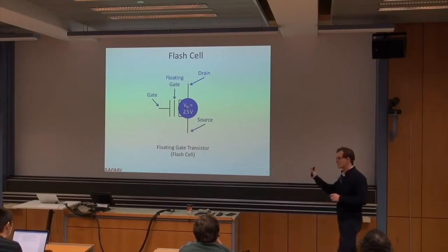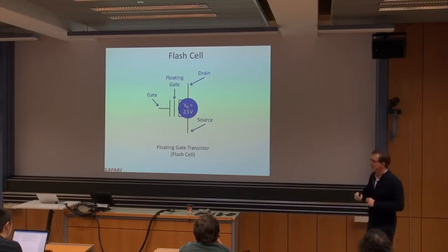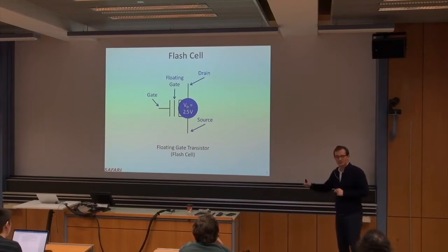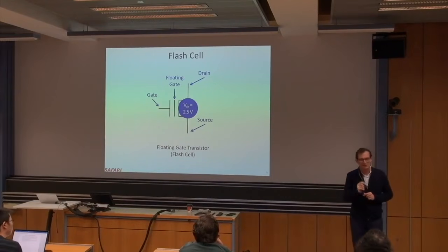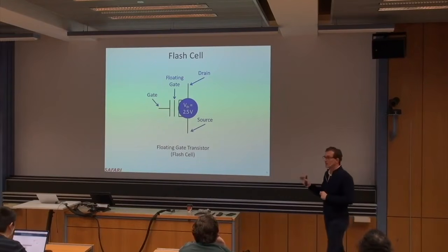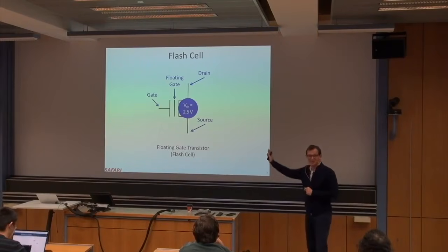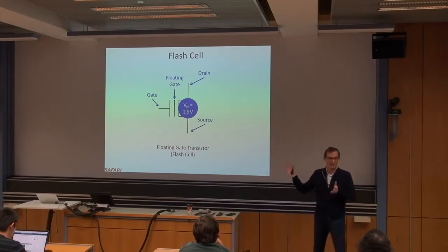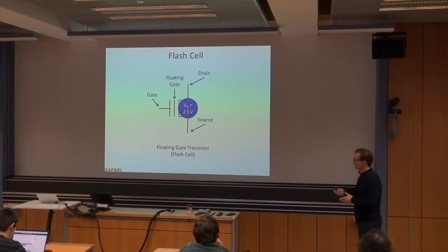If you are interested, you can read some of the papers that I'm going to reference. Incrementally, you increase the voltage step by step, pumping voltage into the cell up to the level that you want, such that that level is encoded as whatever data you want the cell to reflect. We will see that also.